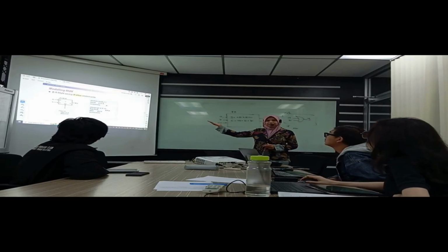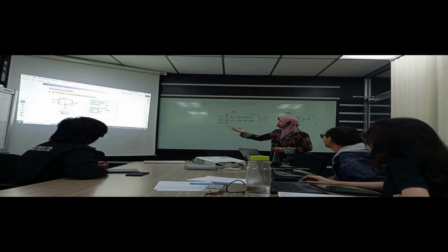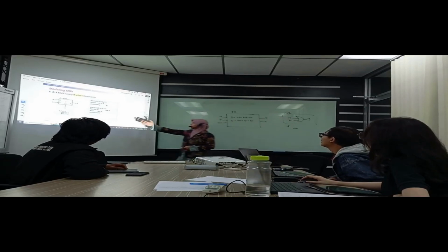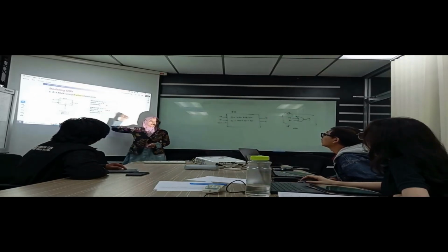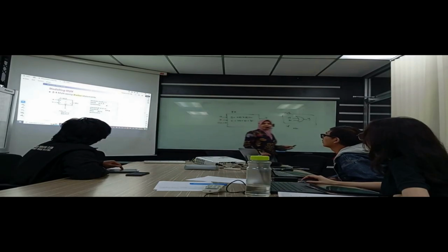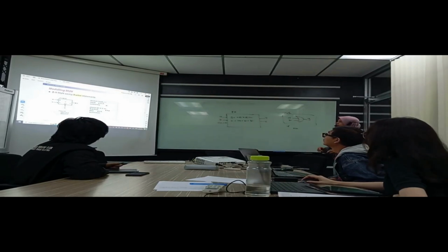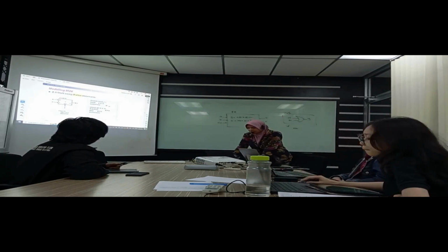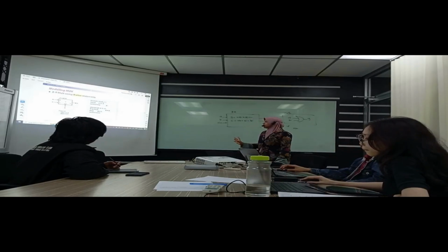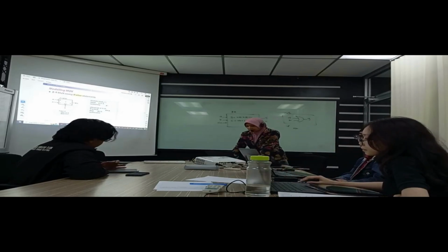It is still output reg, if you use case, right? Because you still use the always keyword. Alright. So as long as the variable inside the always keyword must be reg, either you use if else or the case.